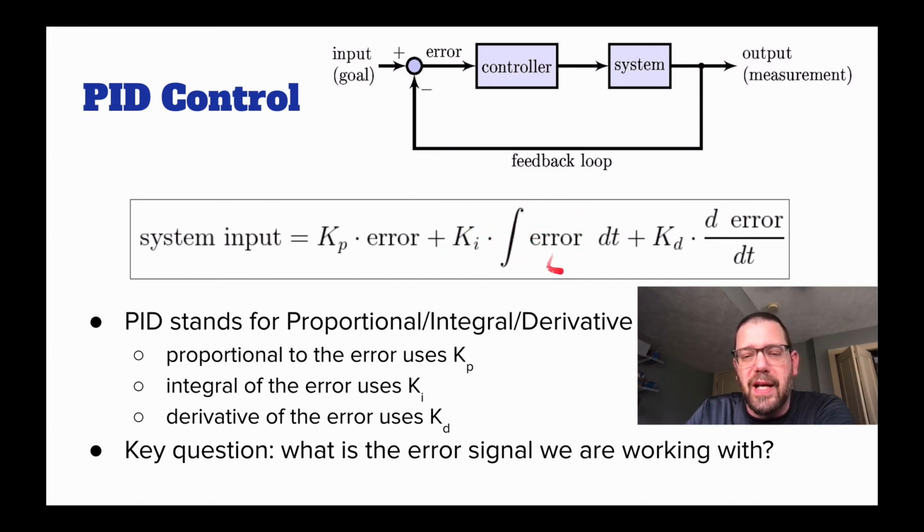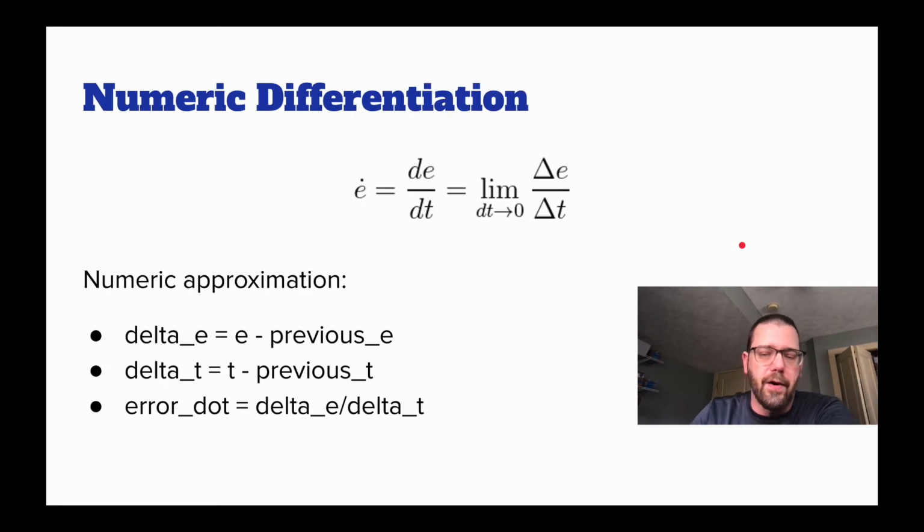That's probably too complicated, and you don't need to be, because there's not any reason to be super accurate in your line following. Being pretty close is fine. So this is an unnecessary complication that we're going to not think about for now. So PD control is going to mean there's a term that's proportional to the error, and there's another term that's proportional to the derivative of the error.